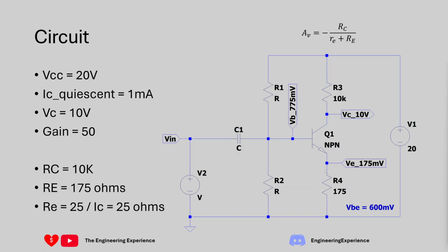So the voltage is created on this by the emitter resistance, and by subtracting that portion from the input signal, we are providing net negative feedback. In this case, the negative feedback will help to reduce distortion and increase input impedance. In the book, it says that the negative feedback will help improve linearity and stability, as well as the input impedance that I mentioned before. So check it out, because it's quite important to understanding NPN transistors and amplifiers. Now let's get on to the question. We're going to be using this information to try and answer this question.